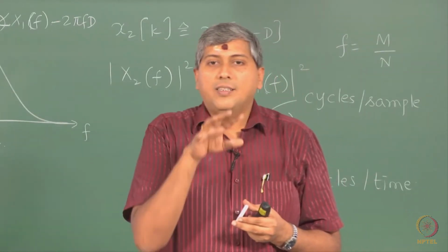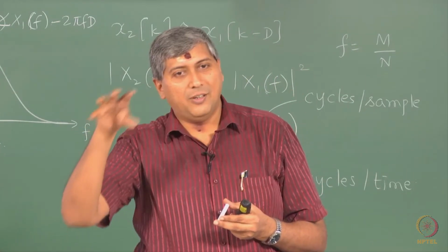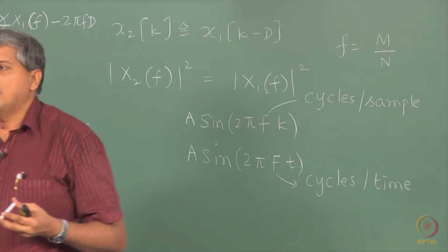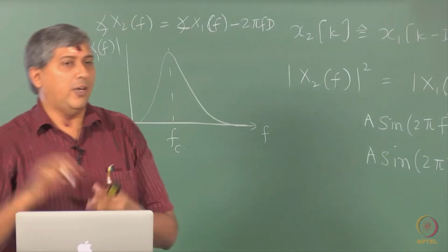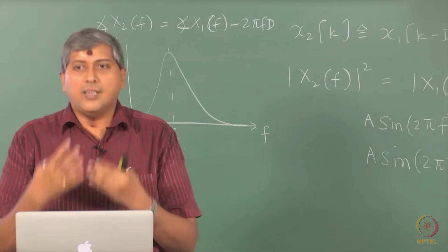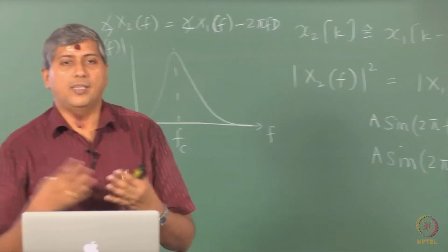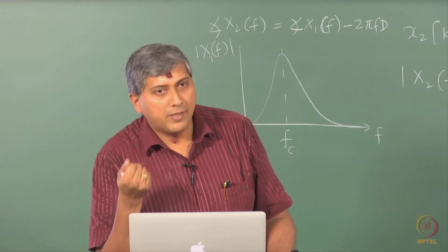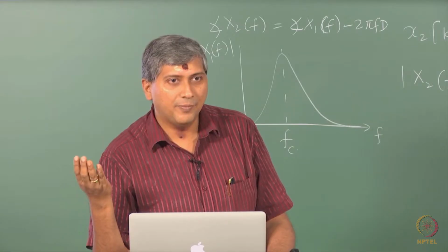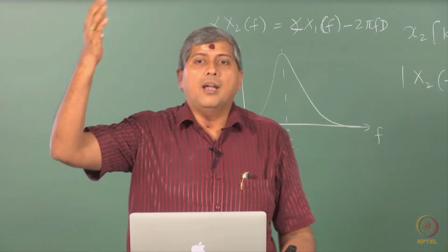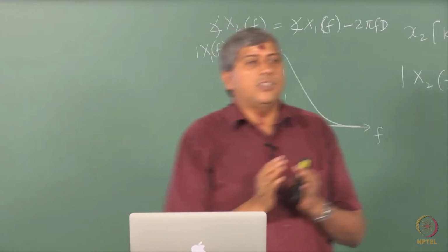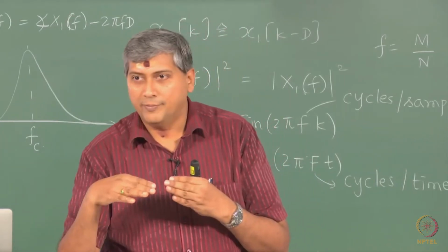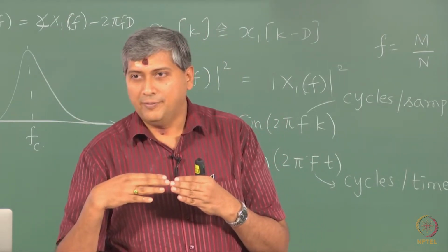So, what is done is, there is a shift of frequency of whatever speech signal that has to be transmitted, and then of course, at the receiving end you will kind of de-shift, you can say. That is essentially the principle in communications, where you wrap the main message in a messenger signal which is of higher frequency. Why do we want to wrap the message into a high frequency signal? Because the losses that occur at high frequencies are lower compared to this low frequency signal, right.